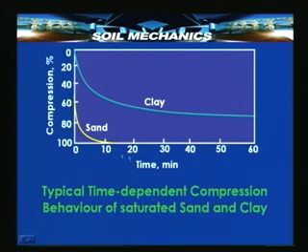What this means is, in clays the compression under load is a time dependent phenomenon. In sands, the compression takes place quite fast, and so fast that for all practical purposes it can be taken as a time independent problem. And therefore, what I am driving at is obvious. Consolidation phenomenon, if we want to discuss, obviously it relates only to the clayey soils, where the compression is time dependent.